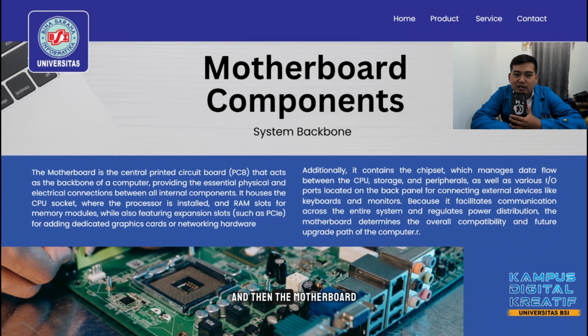And then the motherboard component, or system backbone. The motherboard is the central printed circuit board that acts as the backbone of a computer, providing the essential physical and electrical connection between all internal components. It houses the CPU socket, where the processor is installed, and RAM slots for memory modules, while also featuring expansion slots such as PCIe for adding a dedicated graphics card or networking hardware.